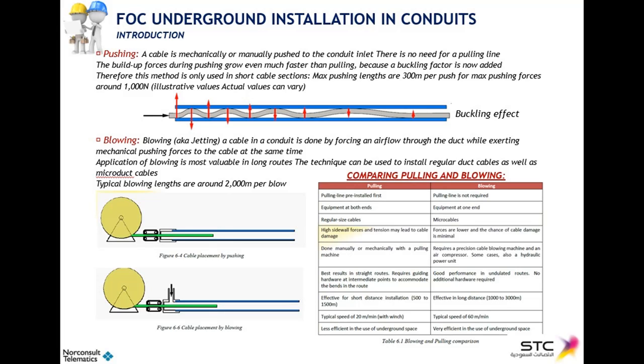However, blowing and this cable floating allows the method to cope as well with bended routes and undulated routes. Therefore, pulling may be effective for short distances, but blowing is effective on much longer distances.